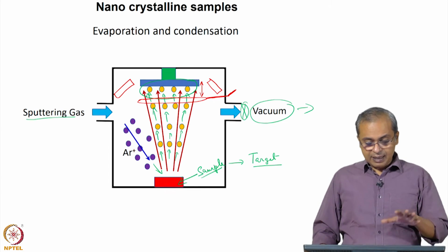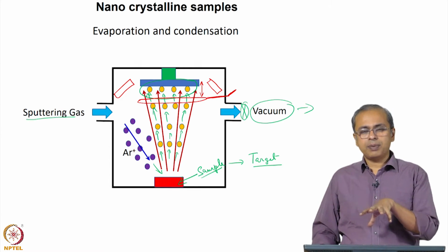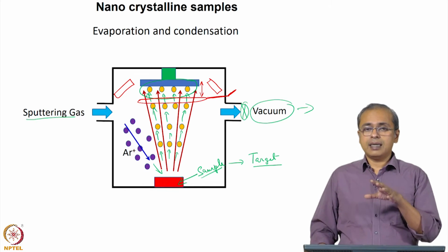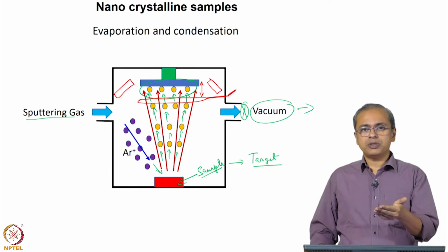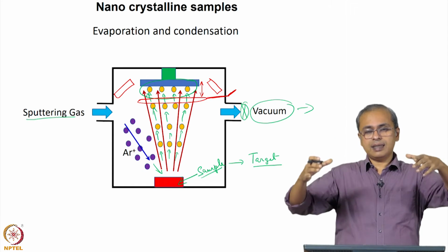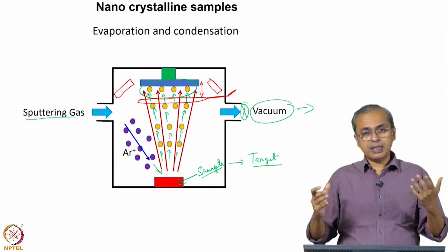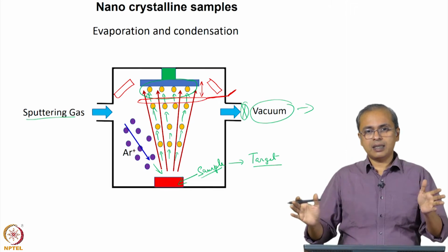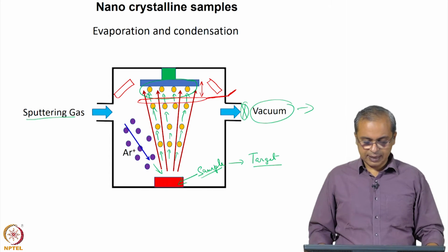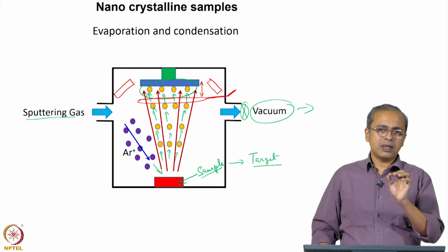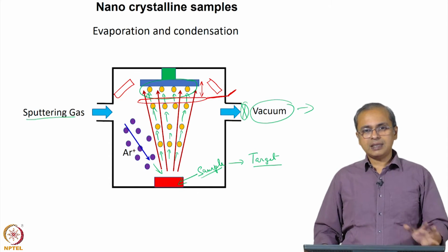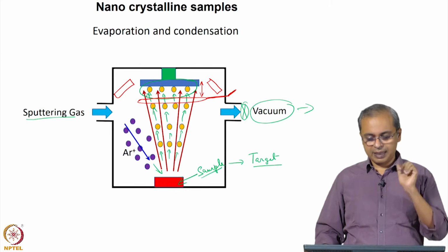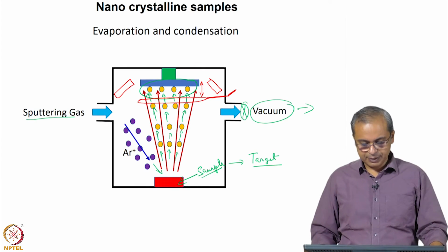And that is what you would do with this system. And in fact with these units, because the process is a bit slow, it is a good idea for you to think ahead of time what kind of samples you want and put multiple substrates in position, so that you can get all of the samples together in one sputtering process. And so those kinds of logistical details you have to pay attention to for you to fully maximize the utility of a sputtering process and get yourself these samples.